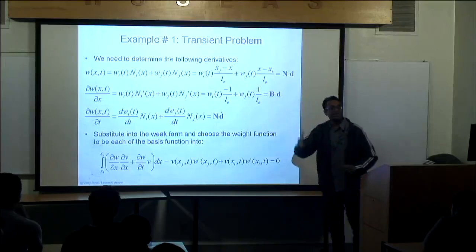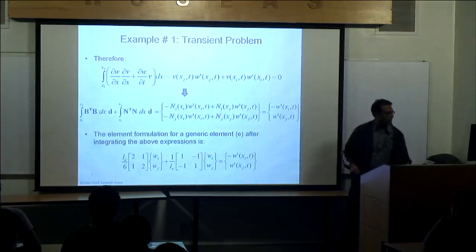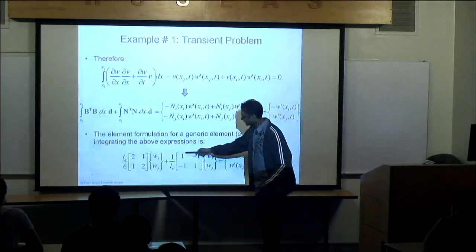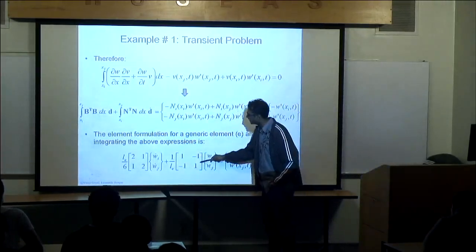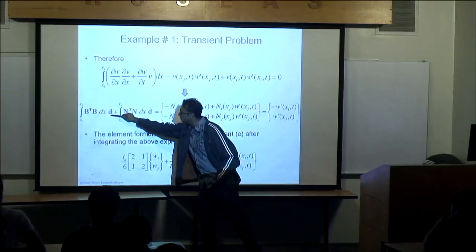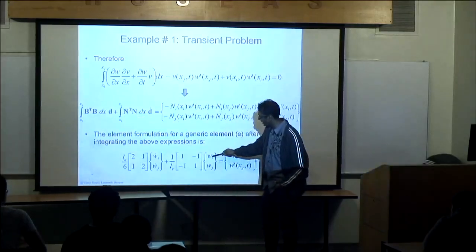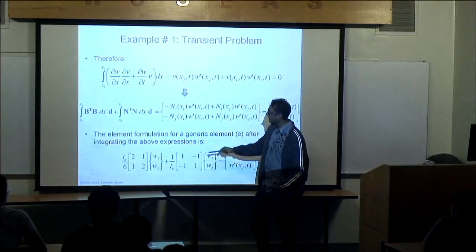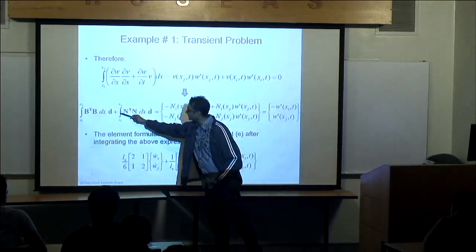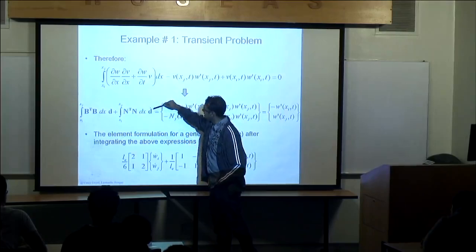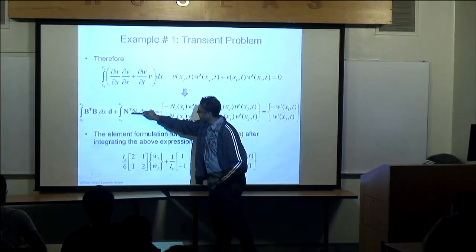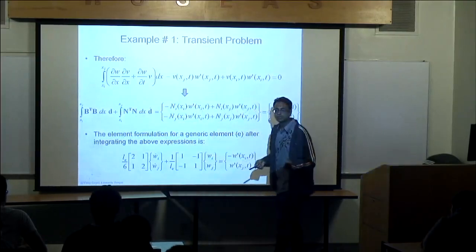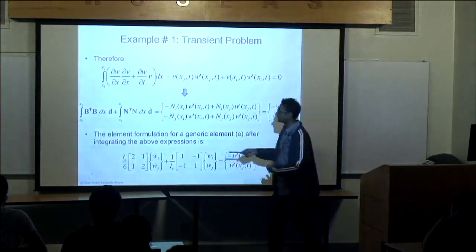Multiply those two, integrate that over the domain, and when you do that, you get this matrix right here, okay? And the D bold right there is basically WI and WJ for node I and for node J. And now I also have to take this integral, which has a D dot there. This N and transpose N are known. We know those. So you can integrate that very quickly from xi to xj.